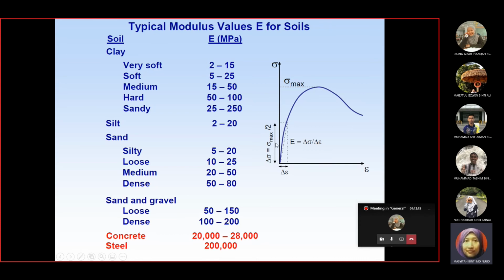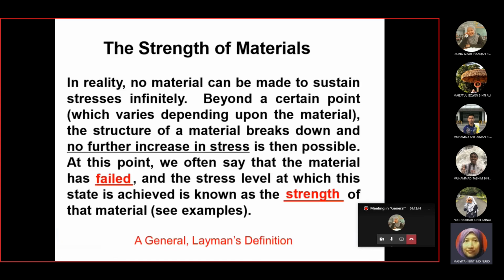So that's why I said you have to read the question carefully, what parameters or which Young modulus it is asking you to use in your design part. Because remember, this subject is related to analysis and design. So when we want to do design, you must do analysis first. For analysis, you must know the input parameters to be used in the calculation, right? What is the value of E, what is the Poisson ratio, if the soil is clay, what type of clay, soft or hard clay.